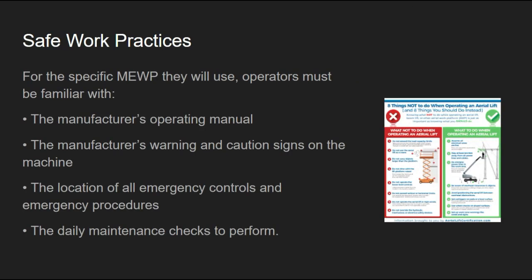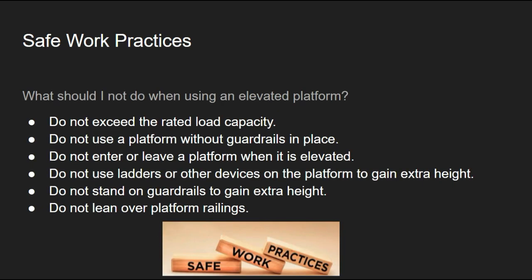For the specific MEWPs you will use, you must be familiar with the manufacturer's operating manual, the manufacturer's warning and caution signs posted on the machine, the location of all emergency controls and emergency procedures, the daily maintenance checks to perform. Here are just some of the things that you should not do when using an elevated work platform.